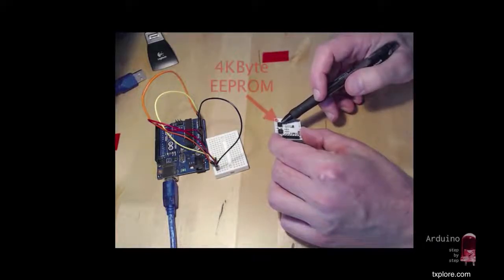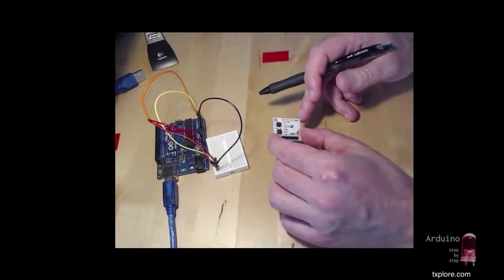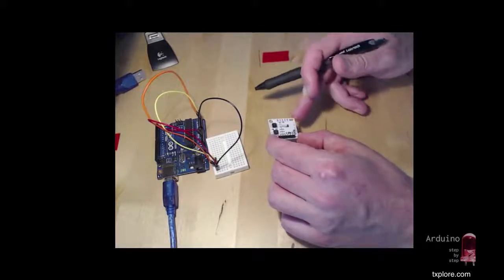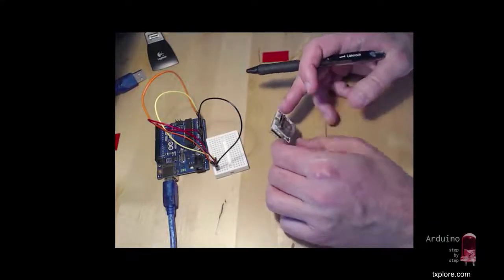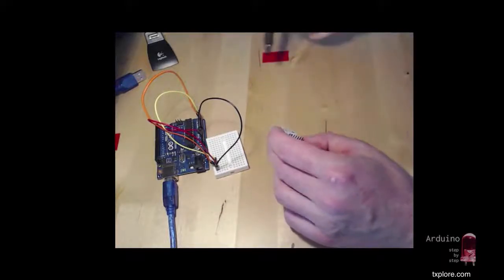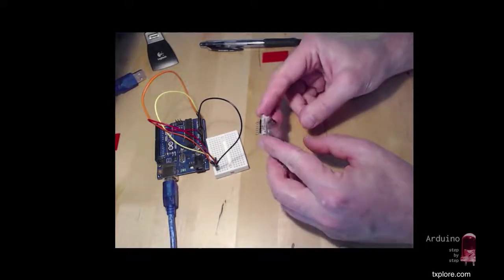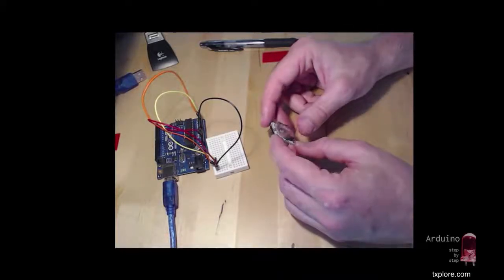This second IC here is an EEPROM, so it provides about 32 kilobytes of memory that you can use for your projects, to extend your sketches. I'm not going to show you how to use this chip yet. I'm going to do another lecture for EEPROMs specifically. The PCB also has a thermometer on it, which again I'm going to show you how to use in another lecture. The PCB also has a socket where I can put in a battery. With this battery, when the PCB is not plugged into your Arduino and taking mains power, you can use battery power to retain the time.